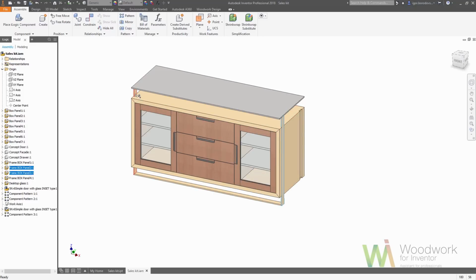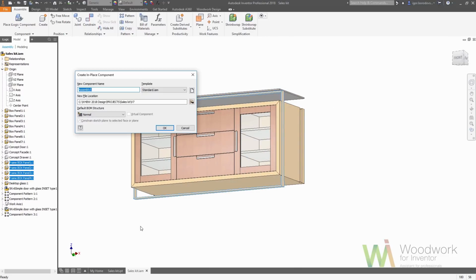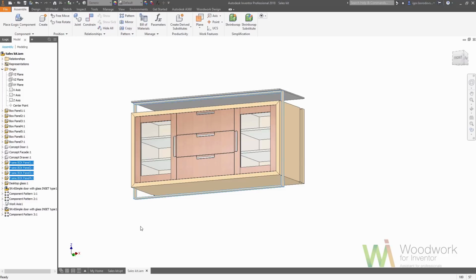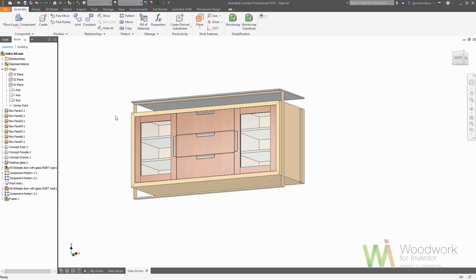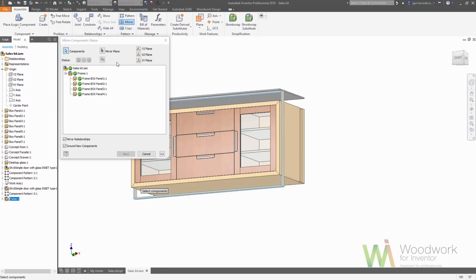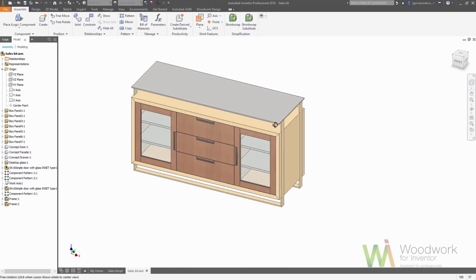The same will happen with the frame, which basically holds the top piece of glass. Okay, we are saying that we want to at first combine those frame components in one single assembly. And once it's done, we can fix the position using the grounded tool. Then we can do a mirror in order to mirror the frame from the front to the back side. Because we are lucky, our model is symmetric, so we can easily do this without any effort.